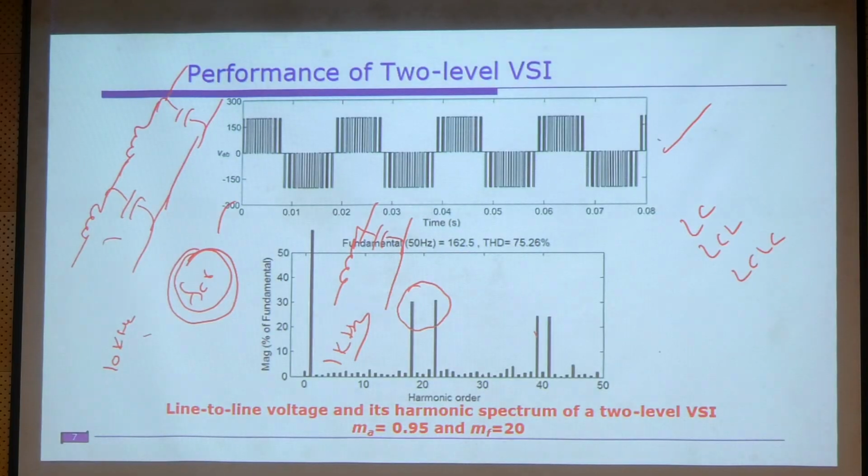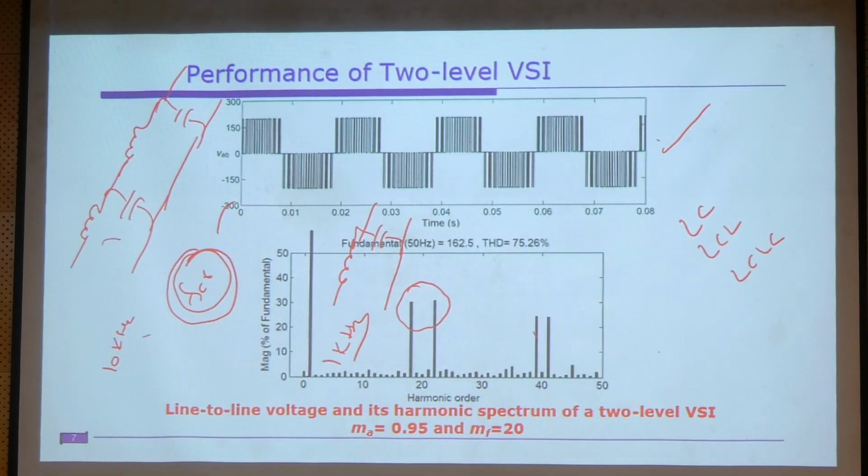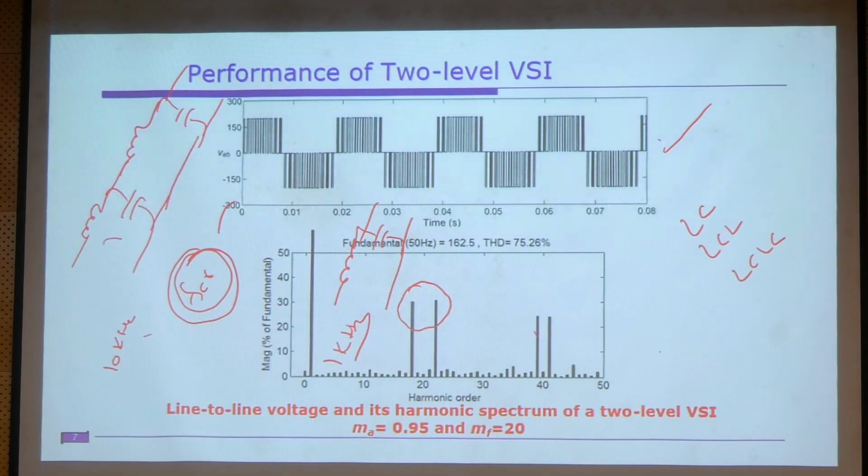In inverters, unlike DC-DC converters, we do not use resonant converters like zero current switching or zero voltage switching. That is not a good idea here because of the size of the passive components, so we will not implement those techniques in the inverters. Therefore, it will lead to higher switching losses.